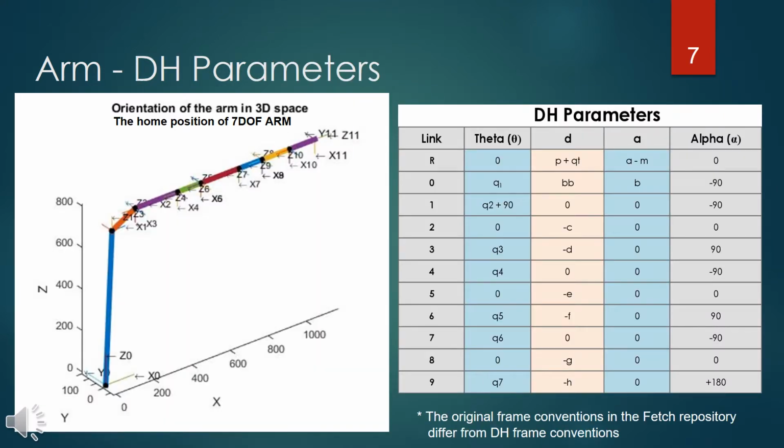As shown in the slide, we derived DH parameters for the robot's arm by assigning the frames for each joint according to the DH convention. We used 3 dummy frames and calculated link transformations from the base link to the gripper link. Here the base link frame is at the midpoint of the line joining the centers of the two wheels. We derived respective dimensions for the robot links mentioned in this figure from the URDF file of the robot.